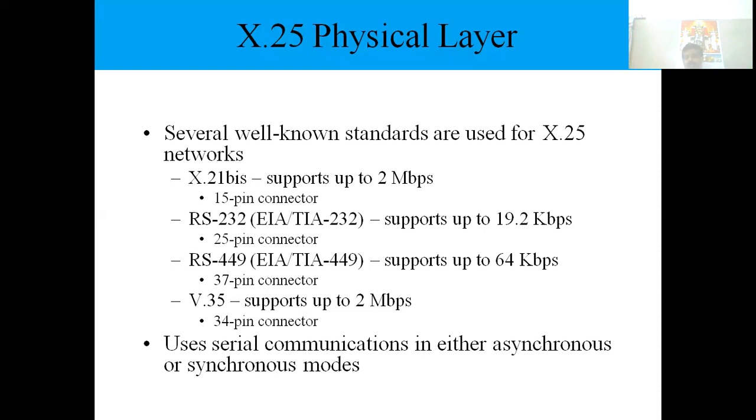What is meant by asynchronous transmission, and what is meant by synchronous transmission? Asynchronous transmission means you will be sending the data with a start bit and a stop bit. There is no timing relationship in asynchronous transmission. But in synchronous transmission, you will not be using a start bit and stop bit, and you will be continually transmitting the data. So in asynchronous mode there will be a gap between the data, and synchronous mode will have a continuous transmission.